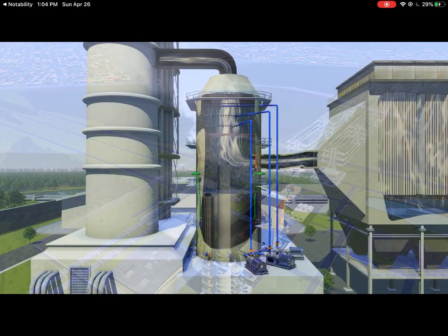The device on the right is an electrostatic precipitator, which we introduced last class for removing particulate matter, right? So you can see that there's a sequence of these devices here. You may imagine, why can't we just remove the sulfur dioxide first and then remove the particles? It is difficult because once we generate the particle-containing flue gas, if we first introduce it into the scrubber, then the droplets will also absorb those particulate matter, and it will affect the grade or quality of the product, which is gypsum in our final product.